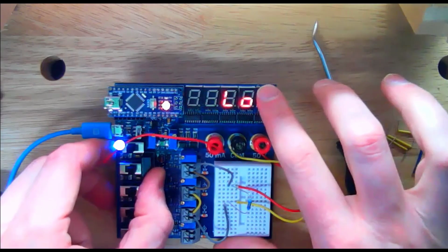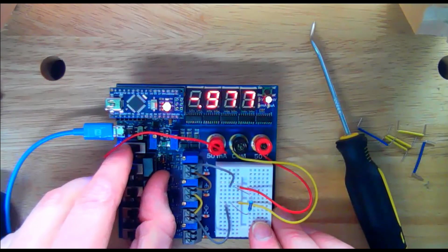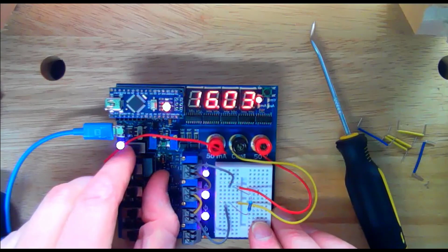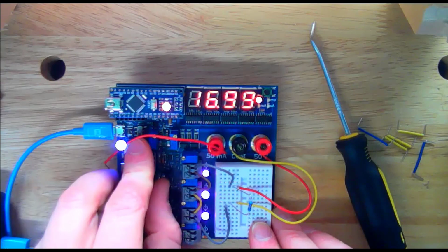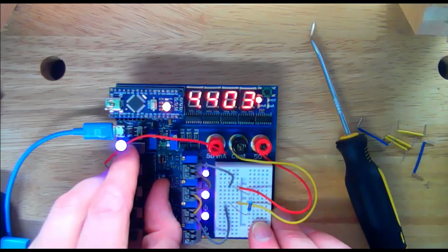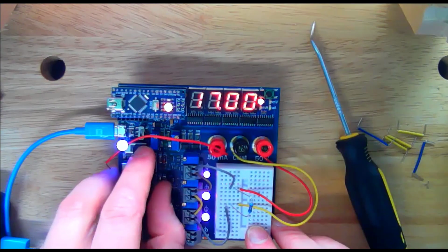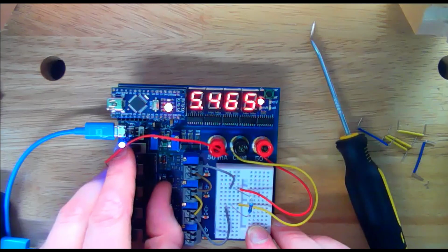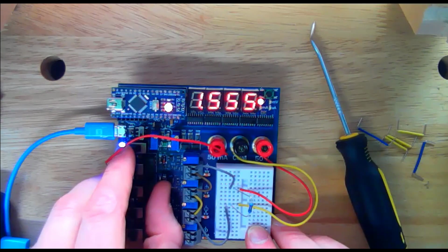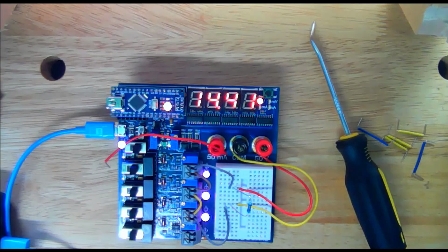Now let's compare to low resolution. Low resolution, so that's millivolts, we're down to point something millivolts. We turn it on, whoop, it jumps basically right up to 17 in low resolution. And it drops almost immediately down into the millivolt range. So low resolution is a faster response to the measurement. High resolution, though, you're going to get a more accurate value. You're going to get a smoother, a less noisy value, I should say. But it takes longer for high resolution to switch back and forth.